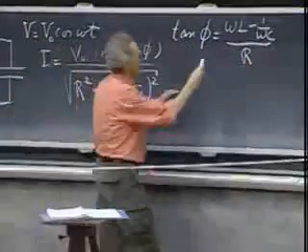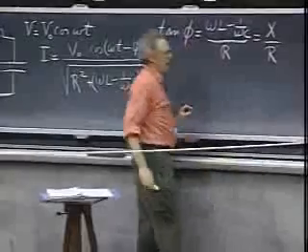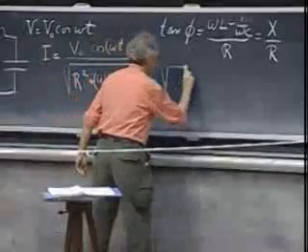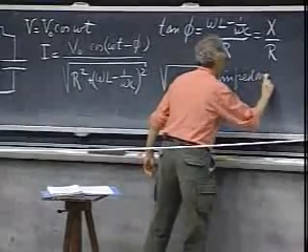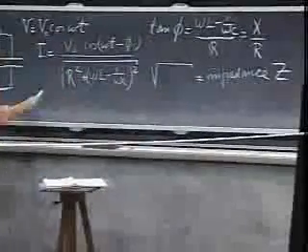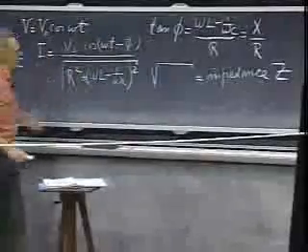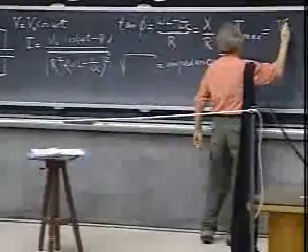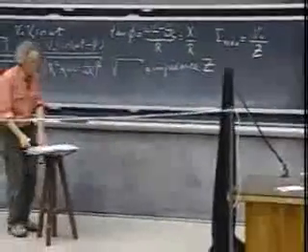We call this the reactance, the upstairs, for which we often give the symbol X, and so this is also X, then divided by R. And this whole square root that we have here, we call that the impedance. The units are ohms, and we call that Z. And so the maximum current that you can have, the current is of course oscillating with angular frequency omega. The maximum value that you can have for the current, which I call I max, is then V0 divided by Z. Then the cosine term is either plus or minus 1.